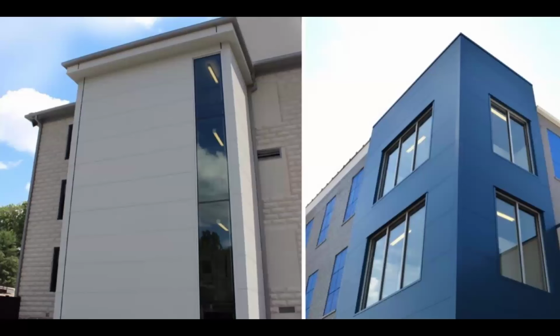So getting into this a little bit, here's a couple of examples. I will say IMPs are sort of limited products, especially if you're considering them as the finished element, which these two pictures show. Panels are going to be typically 3.5 feet wide. You can get some architectural fabrication integrated into these panel systems, but they're very wide. They have a different monolithic scale to them than a lot of the other panels that you might look at in metal skins. And then the other thing is, you can see here from these two pictures, virtually no shadow lines, no depth to the profile or corrugations.